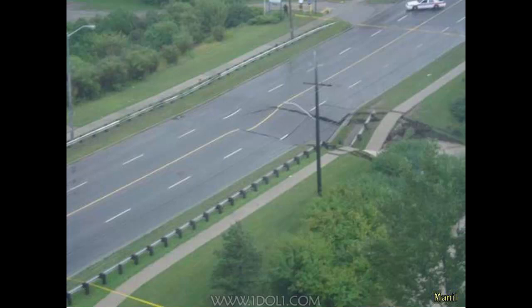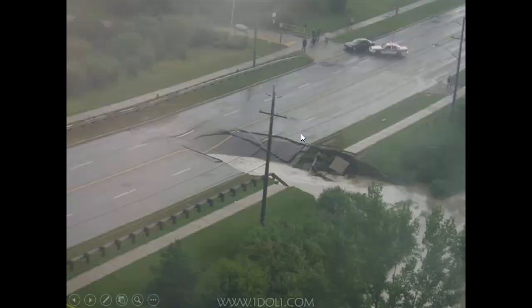Not only through it, but water was seeping through the soil that the culvert was embedded in, and it was washing out some of the soil particles, so there was what's called piping, where actually the soil that's around the culvert got washed downstream, and then it collapses, and now the water can seep at a higher velocity, and it has even greater scour potential, and so it eroded and undermined the entire foundation of the road underneath the culvert.